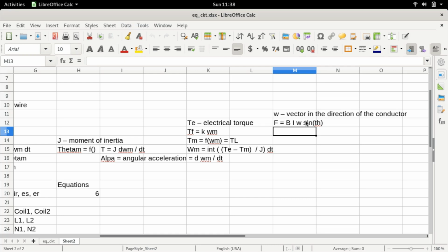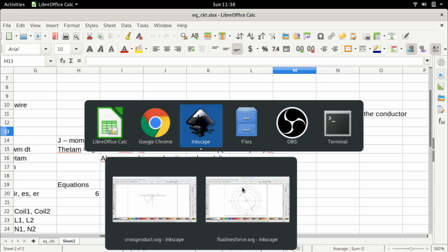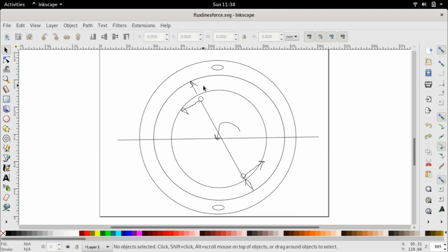So now that we have resulted in a mechanical force, if we go back to our original diagram, this is what we had discussed of a single phase induction motor. This is a simplified representation of a single phase induction motor, where we had said that all the stator windings are concentrated in these 2 slots diametrically opposite each other. In reality, there will be slots all over the stator, but for simplified explanation, this is good enough. And we had said that all the rotor bars are also concentrated diametrically opposite each other, whereas in reality they are all over the place.